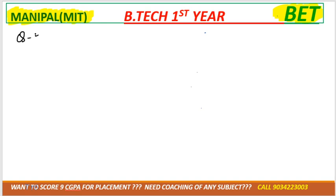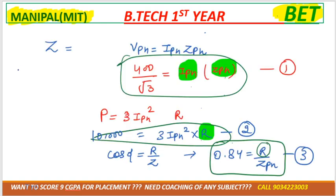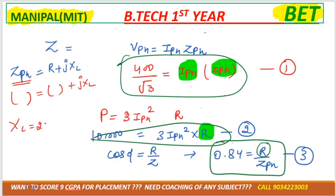In question number 2, from here you will get the value for ZPH, right? So ZPH is how much? R plus jXL, right? ZPH you know, R you know, then you will also get to know XL, correct? And after getting XL, XL equals 2 pi FL. So 2 pi F you know, XL you know, you will be able to get L easily. And they said it should be in millihenry, so you need to convert it into millihenry, okay?